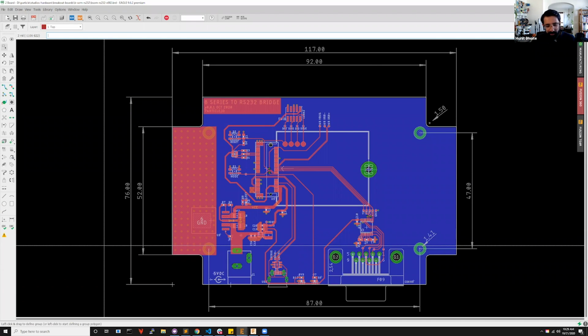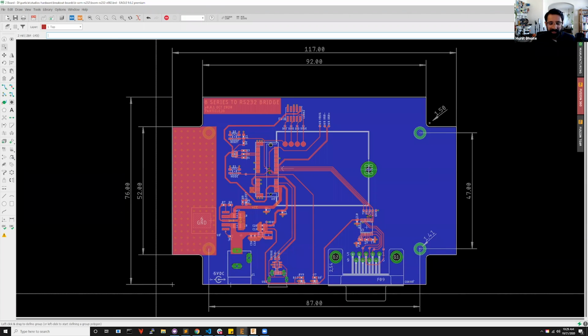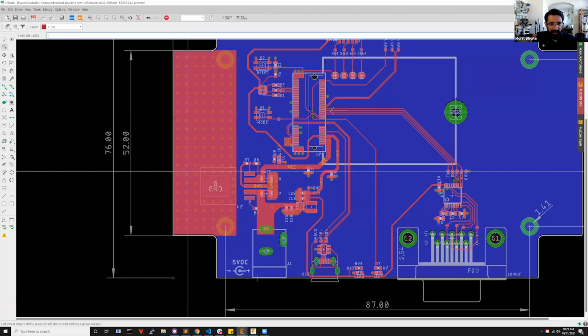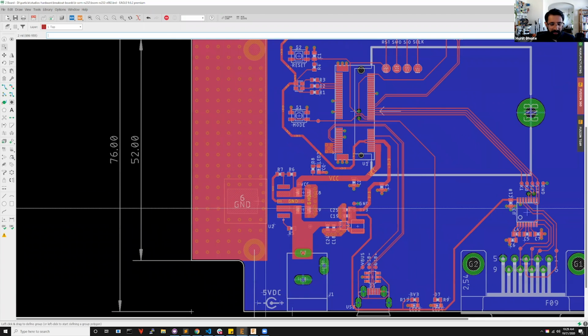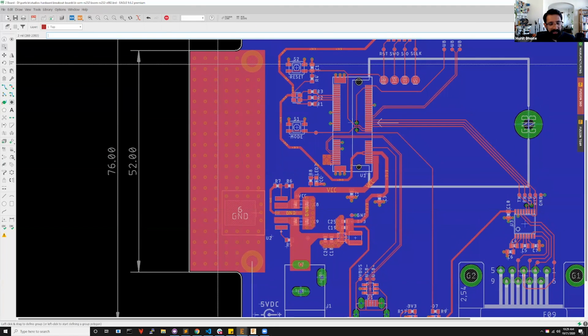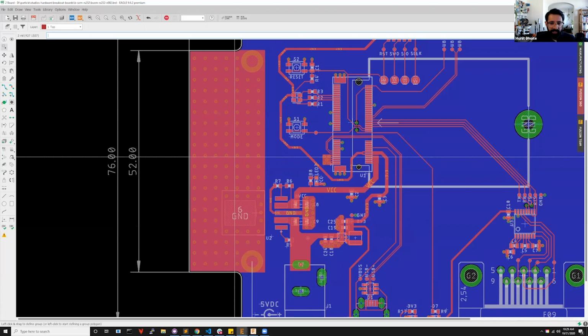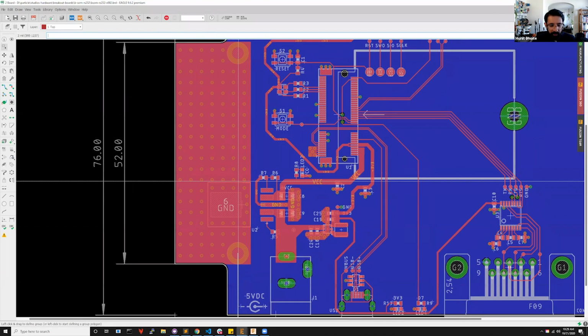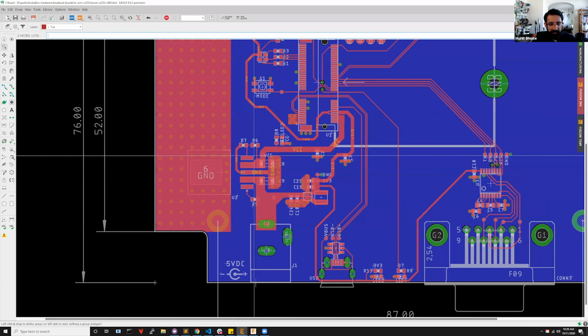This is where the actual fun begins. It's like playing Tetris all day. You're routing and rerouting boards. And so right now over here we have an LDO, which is a low dropout linear regulator, and we have given it ample copper to dissipate any additional heat, using power planes to bring power in and out of the regulator.